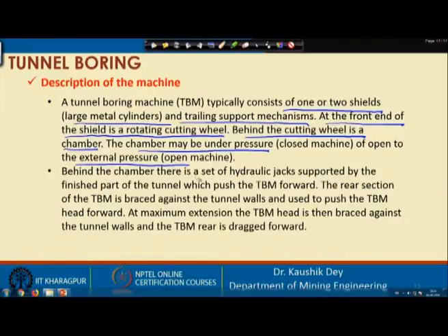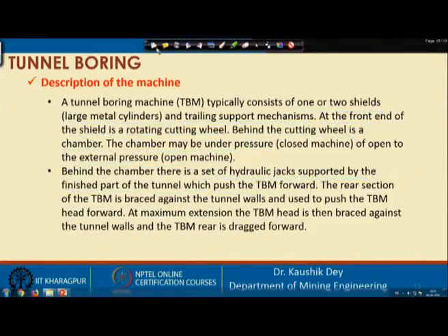Behind the chamber there is a set of hydraulic jacks which provide the support to the finished part of the tunnel, and TBM is being advanced against this support by the hydraulic push. So, basically the back part, if this is the tunnel and at the mouth this is the cutting head, this back part is supported, and this cutting head is being forced hydraulically from this support to the front direction. So, that is the drag force observed in the TBM.